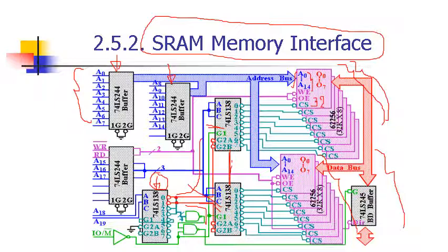So we'll take from A0 to A14, but we buffer these, so we need 15 different pins. 8 of them are buffered through this buffer, and the other 7 are buffered as well in the other buffer, and they are provided through these buffers to your memory chip. So these are the 15 required pins connected to each of your pages or each of your memory chips. Good. How about the rest?